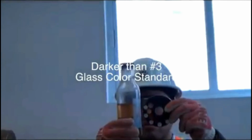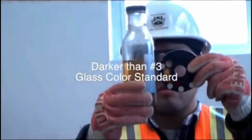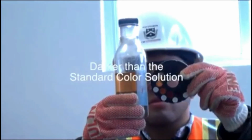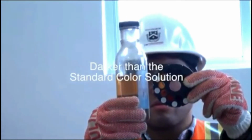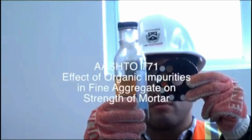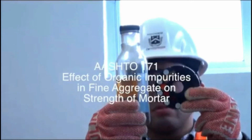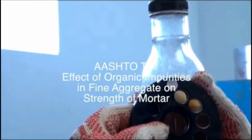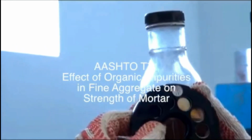If the liquid has produced a color darker than the number 3 glass color standard, or darker than the standard color solution, additional tests may be necessary, such as AASHTO T71, effect of organic impurities in fine aggregate on strength of mortar.